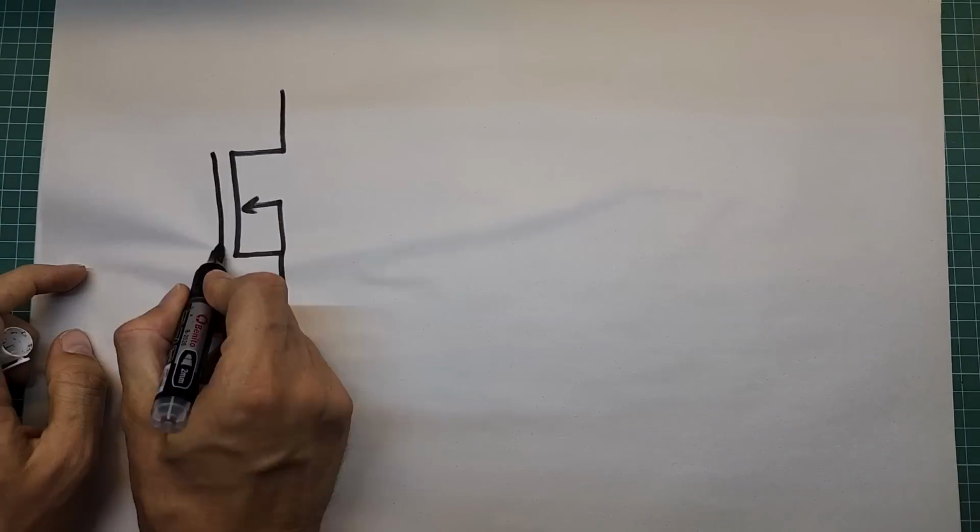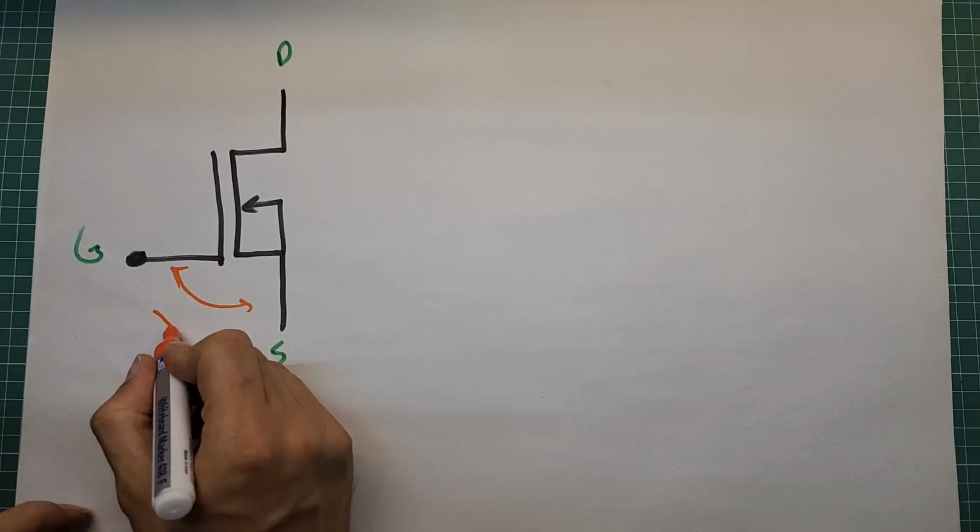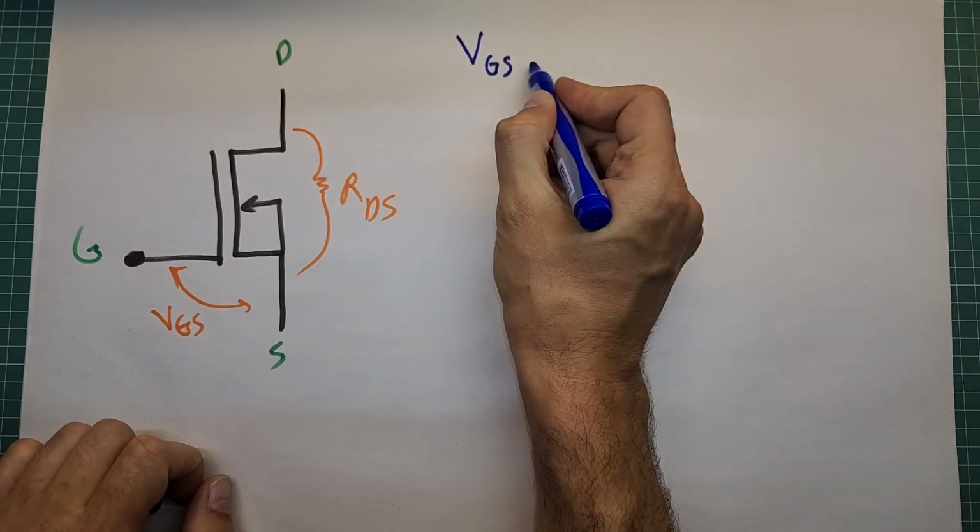Creating fast and quick transitions in the switching signal, along with some other factors, will make the biasing circuitry of a MOSFET more complex compared to that of BJTs. Actually, in many cases, MOSFET driver ICs are used for making those transitions quick and sharp. Now, you may ask about the importance of these quick transitions. You may ask why I have to make transitions quick and what the consequences of ignoring that are. Let me explain.